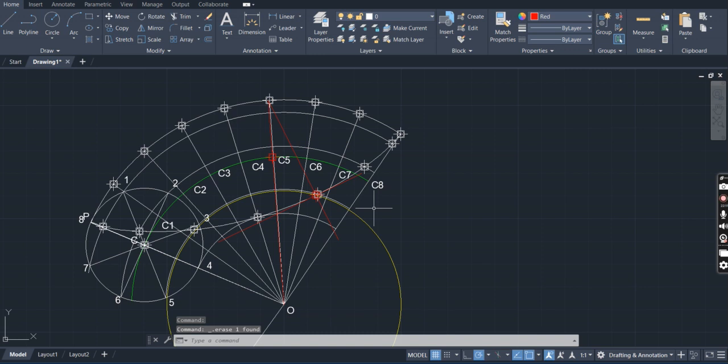And now I want to highlight the things. That means I want to highlight one arc, the hypocycloid, tangent, and normal. For that, I am using one command, PE. Enter. Multiple. Click on multiple. Select this line, this tangent, and this curve at a time. Enter.